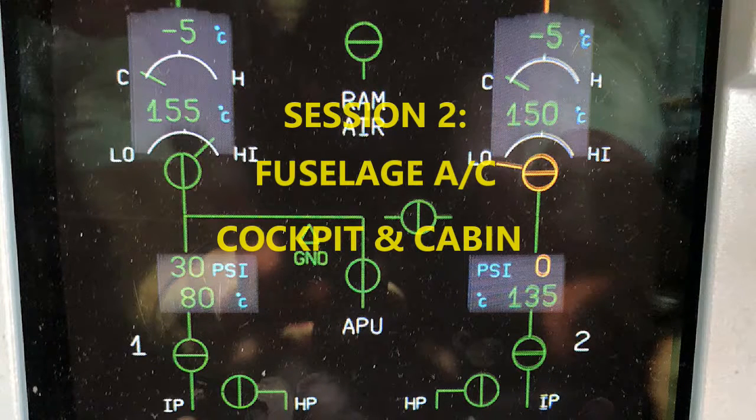So in case you get asked on a test, what's one of the major components of the air conditioning pack? And you see the word condenser, that's going to be an answer. Or primary heat exchanger, that's an answer too. Water extractor, same thing. And of course, along the way, you're going to have downstream check valves. These check valves are going to be installed between the condensers and the mixture unit. And then you also have fan plenums.